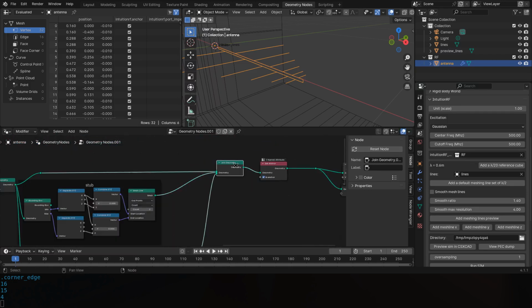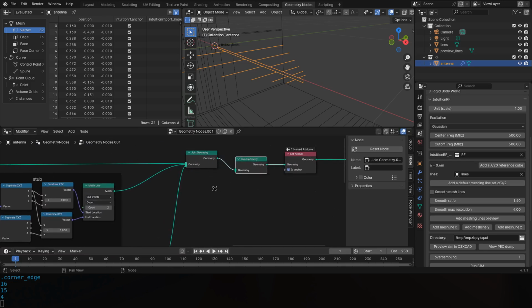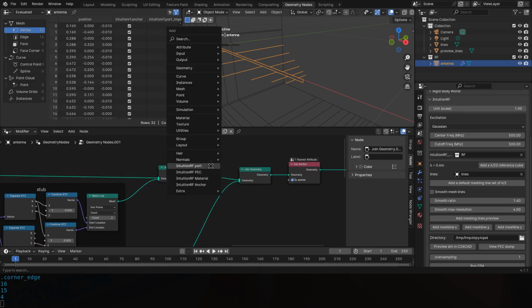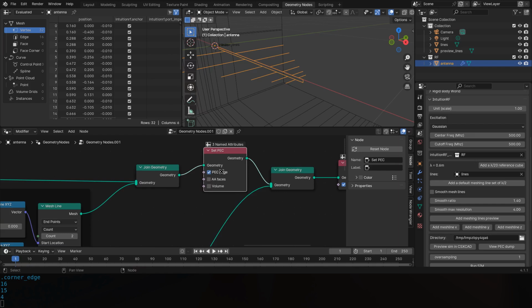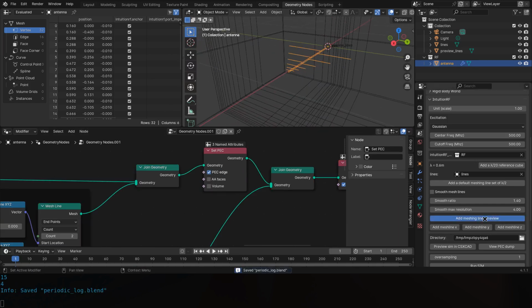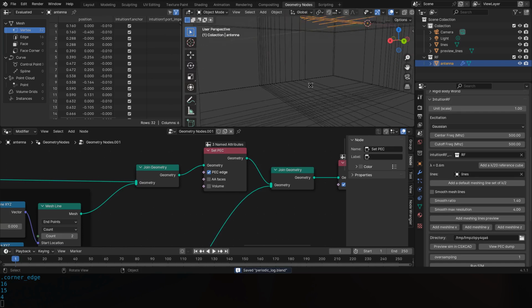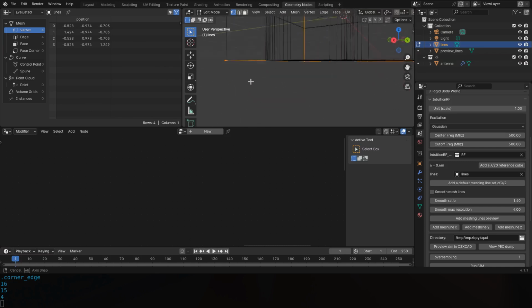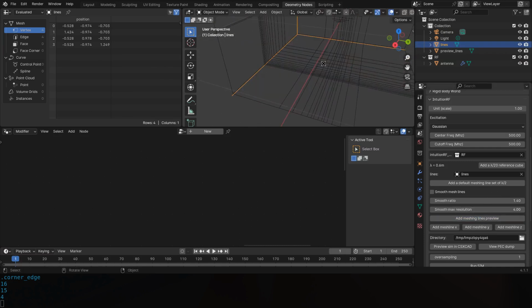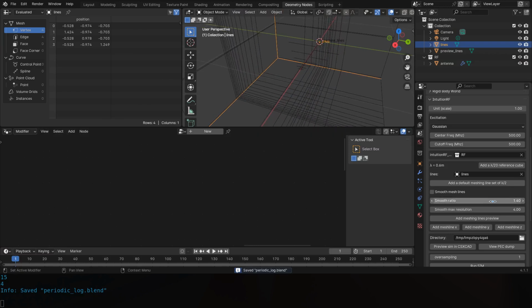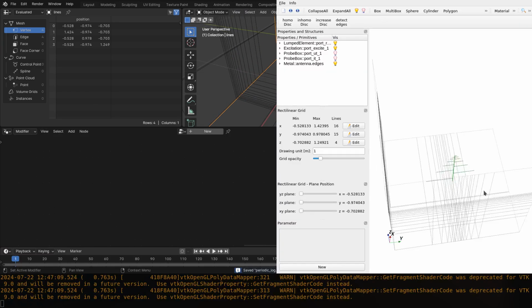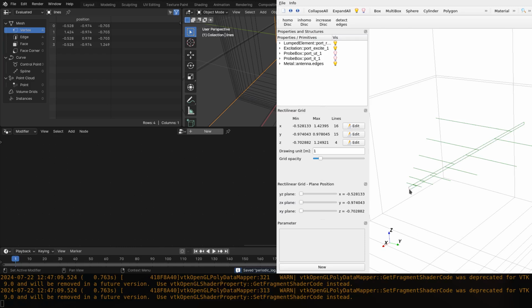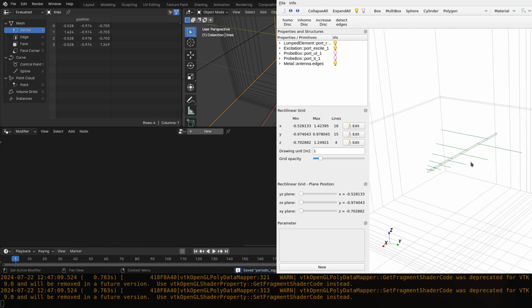And everything else, let's duplicate this, make it like this, and then everything else here is a perfect electrical conductor of type edge. Meshing line is still good. And now we can see something's going on here. I don't know exactly why. Okay. Anyway, preview in CSX-CAD, and now you can see our antenna is defined. And we can see the port element and the metal edges.